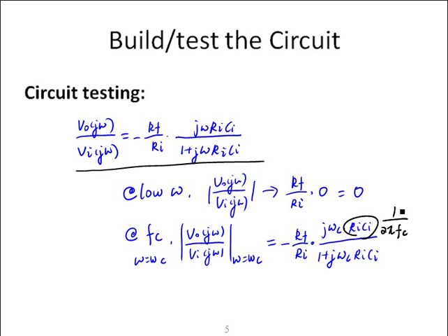On the other hand, the angular frequency omega c is related to the cutoff frequency by 2 pi, so those two are crossed out, and the transfer function becomes negative 1 times j over 1 plus j. Calculate the magnitude of this complex number, we get 0.707, which means the output is 70% of the original input magnitude.